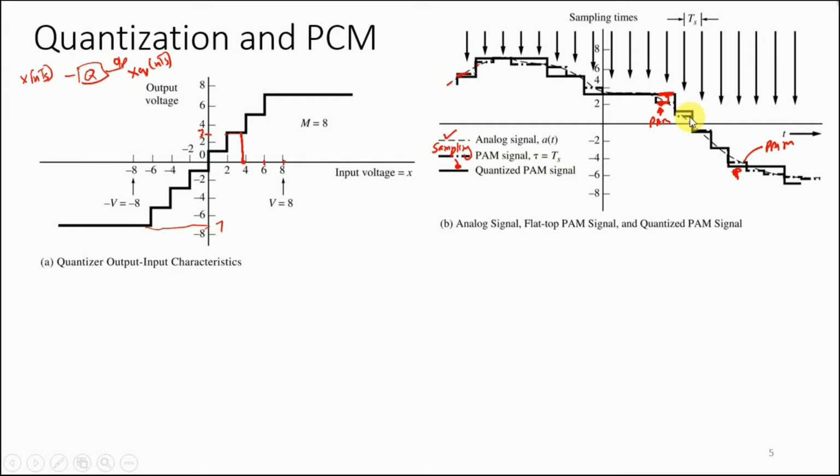Note that quantization is very similar to the rounding of numbers. If we have 1.7, we approximate it to 2. At the same time, if we have 1.9, again we approximate it to 2. So we can do this approximation, but we cannot recover our original signal. We have lost it. If it was 1.9 we got 2, but this 2 is also representing 1.7. So once we have done the approximation, there is no turning back. This means we are going to have a quantization error no matter what.